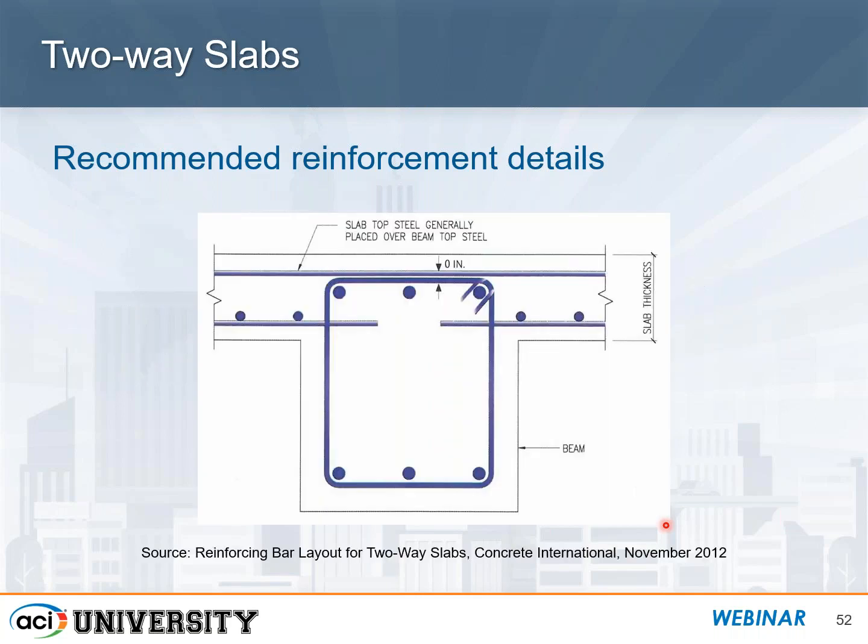So if we look at that typical detail, this is the top reinforcement that's in the slab. We're showing 0 inches here, being at the same elevation as the stirrup, so it's a fit in between where the stirrups are spaced. Again, simple drawing, but if the covers aren't called out and certain other things are not called out, it could cause an issue.